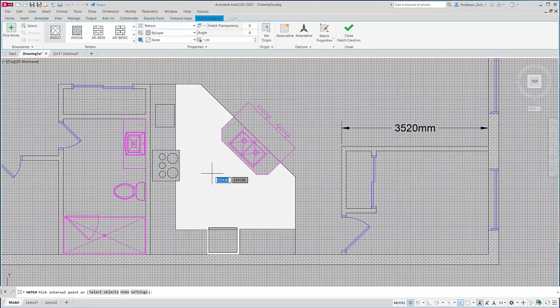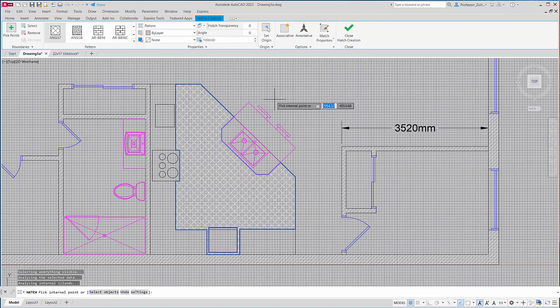And once again, it's solid white even though I picked a pattern. Why? Because the hatch value, the scale value, is too low. So once again here, I'll try starting at 1,000. I found that earlier. It seemed to work, and it seems to work. Can I scale that precisely? You could. To a specific size.